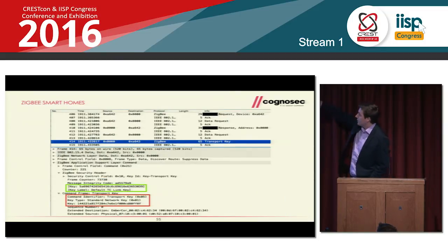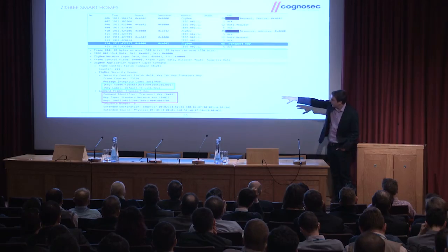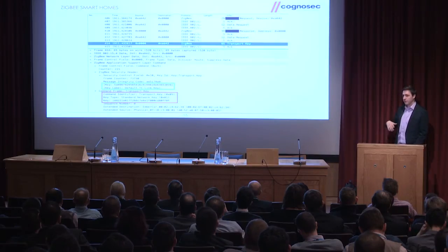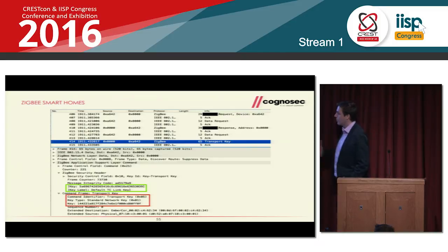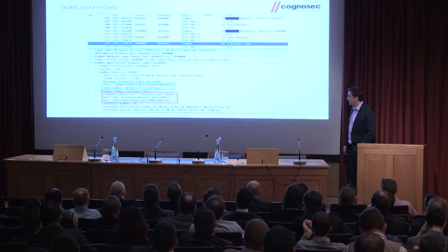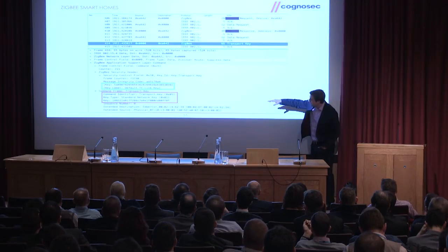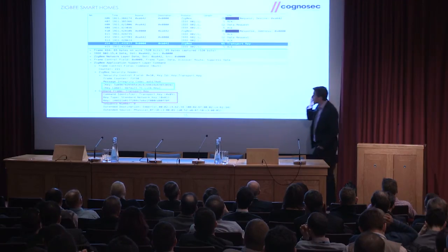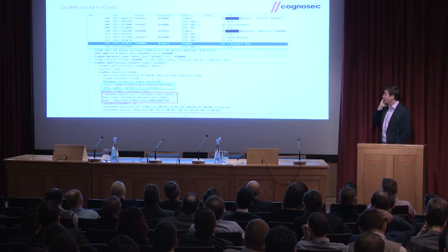And it will trigger a key transport, and you see I labeled the keys in Wireshark correctly, so it's the default trust center link key used for encryption. Wireshark just tries all known or programmed keys and maps it correctly. And then you see, okay, that's the standard network key being transmitted, the network key of our testing system. So it's still the same, and it's very easy.